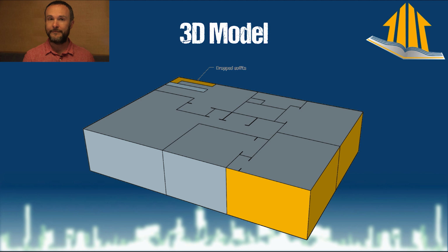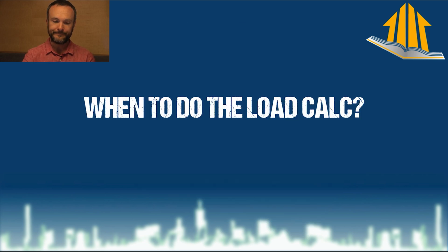In general, from now on, I'm only going to be talking about room by room loads, because block load is something that you can just do if you just want to know how off is the system that is installed in this house. Great, do a block load. If you are like, hey, maybe I should replace my system with something that's smaller, do a block load. Great, that's fine. But if you are going to be doing any duct design or duct installation, you want to do a room by room.